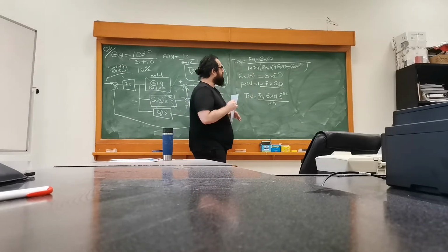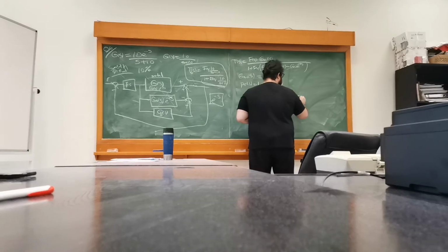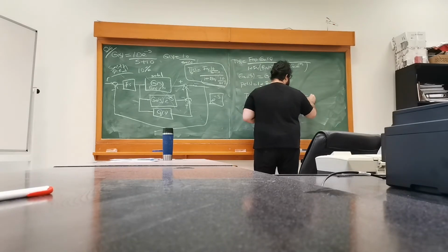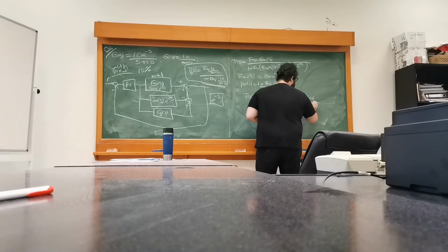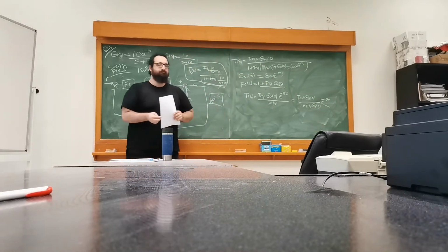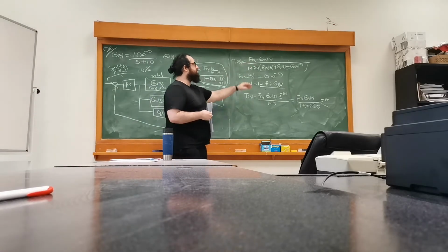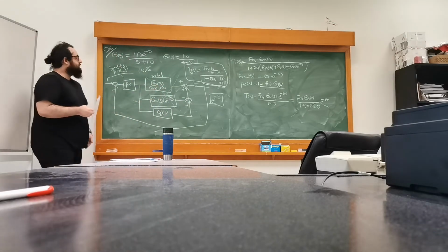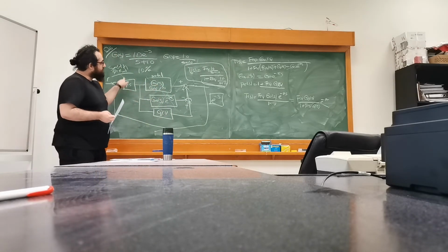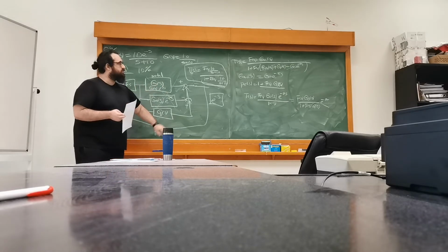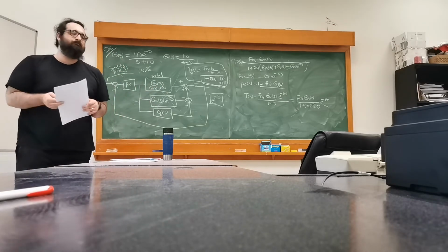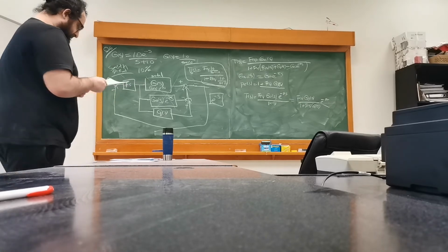I want to design a controller that gives F(s) G0(s) over 1 plus F(s) G0(s), but I will still have this delay part. I cannot get rid of it because it's in the feed-forward path. So even if there's a cancellation here, the overall closed loop will still have this e^(-τs), but I'm still okay with that. It's not really that big of a deal.